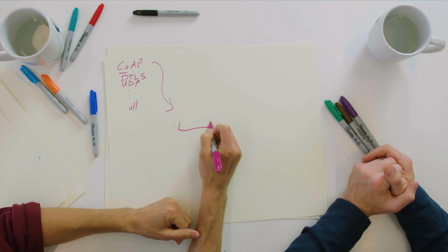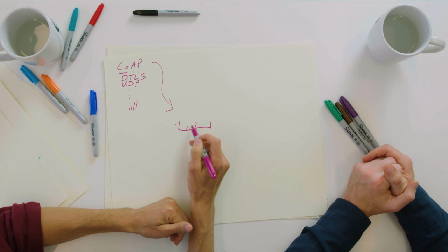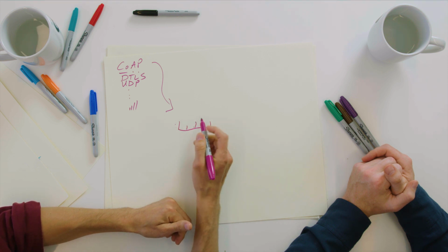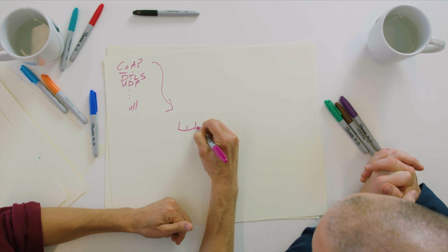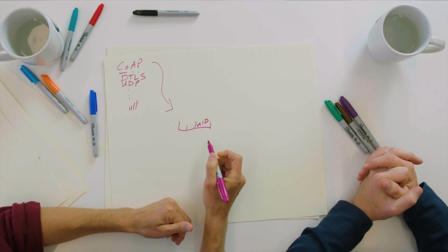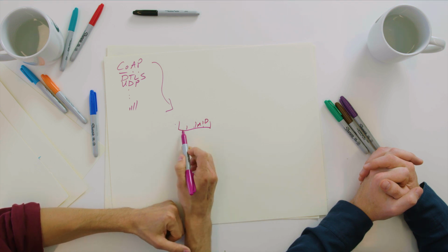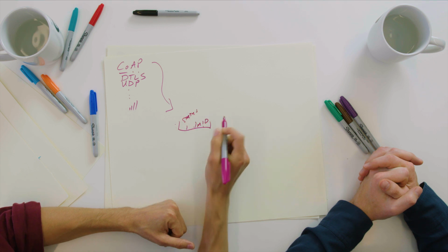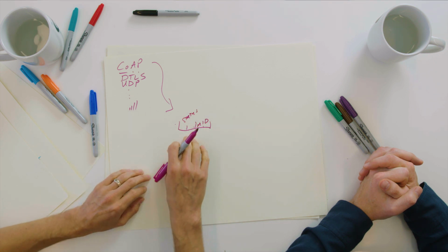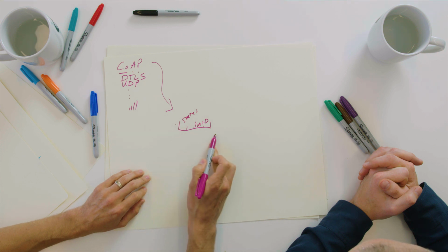The first 4 bytes of the CoAP message are a couple of header bytes that are things like what version of CoAP are you using, and a length field that matters for later. And then there's a message ID for a couple of bytes. There's also a status code built into some of these early bytes, and it's to get an idea of how constrained we're trying to be, making use of every single byte here.